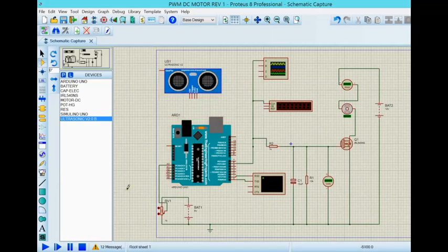Actually, I can certainly use this as my set point for my vessel, and whatever you adjust on this is the PV. This is the actual value, the level that you have, and this is the set point that you want to have. So within the code and the proper constant for your controller output, that will be required to adjust the pulse width and so forth.